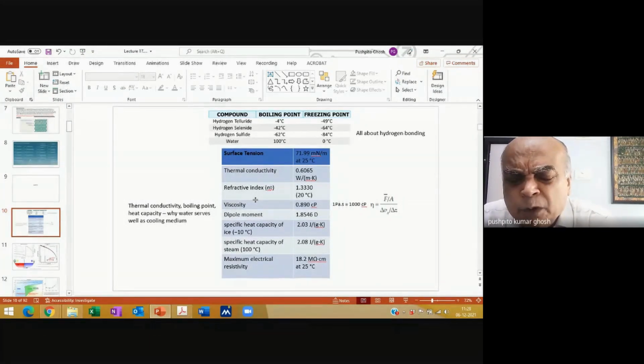We are talking about impurities like DMF and things which remain from a membrane making process. It's so important that even traces of DMF alter the refractive index, and you can actually today have equipment where you can measure comfortably the refractive index up to 4 decimal point accuracy. These trace changes because of impurities, you will be able to actually monitor with refractive index.